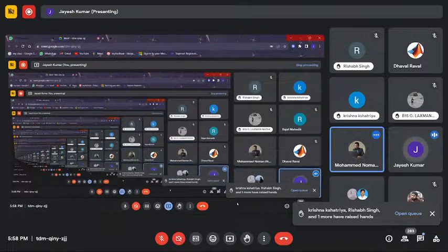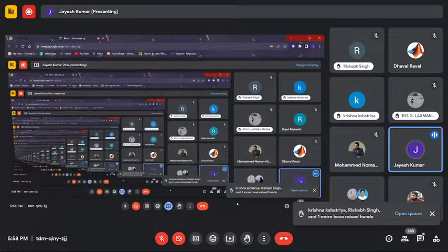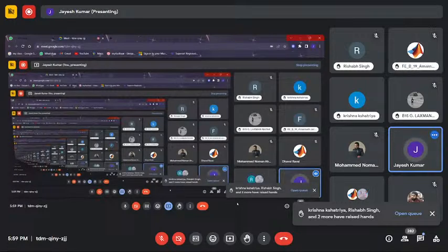Yeah, while cells are connected in a string, they should be in series connection, or maybe in series-parallel connection, where each cell is connected to the positive of the next. While charging the string connections, in lithium batteries you always need a BMS, where we provide passive cell balancing or active cell balancing as per the BMS architecture. But in the ring system, the battery is connected in a loop connection, and one of the parts will always be a connection loss.